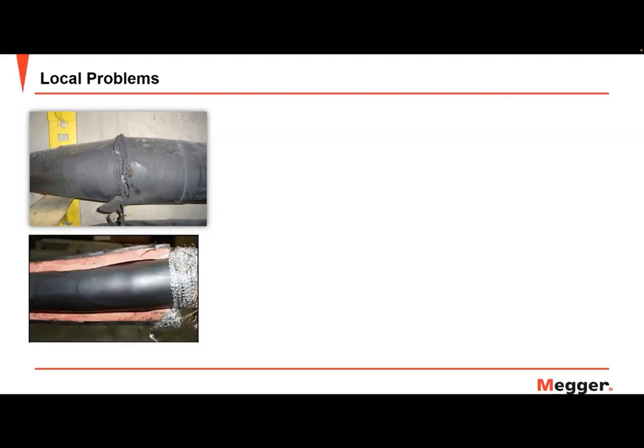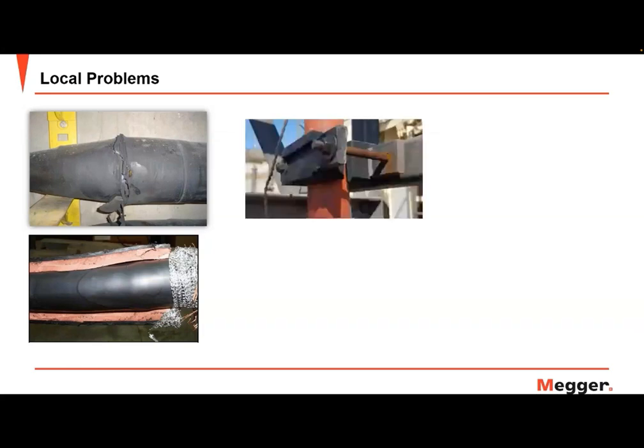Now next, we do have a medium voltage cable here where you can see that we have a heat shrink splice, and that splice wasn't heated all the way to be totally uniform or connected to the cable insulation there. And if we look, we can actually see resulted tracking, and you can see the cavity that's created there, partial discharge activity taking place, and you can actually see that tracking on the cable insulation itself. Next is an example of clamping a cable.